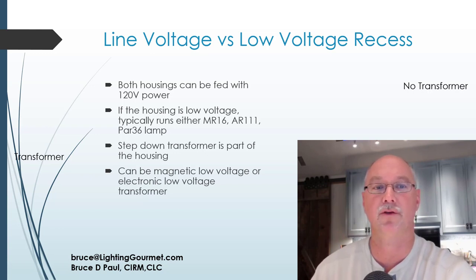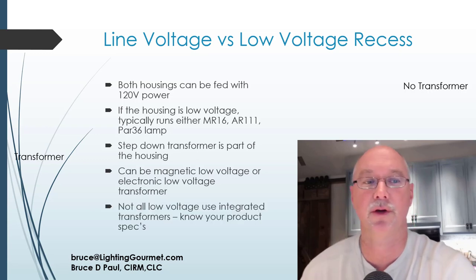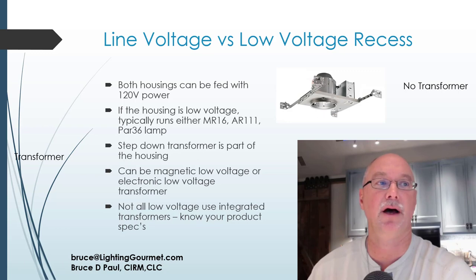Electronic transformers are less expensive. But for sure, not all low voltage cans use integrated transformers, so you've got to understand what you're doing and all the details on it. A picture of a non-low voltage 4-inch can is over here above my head. There's no transformer in that product.